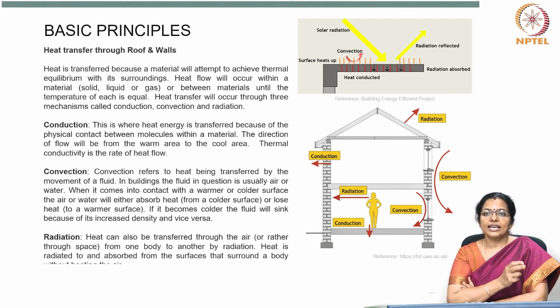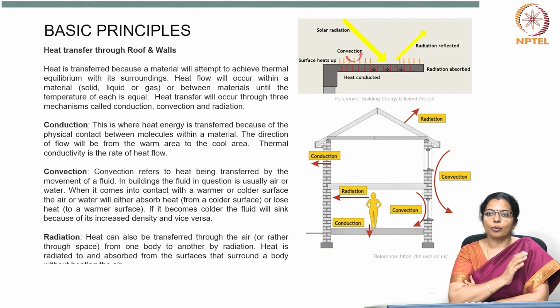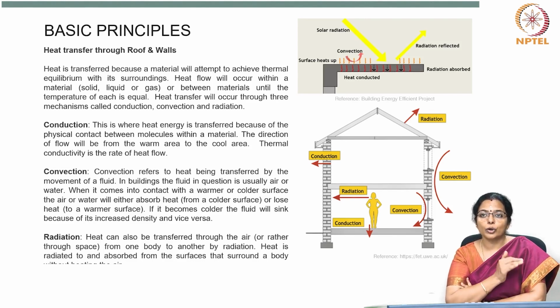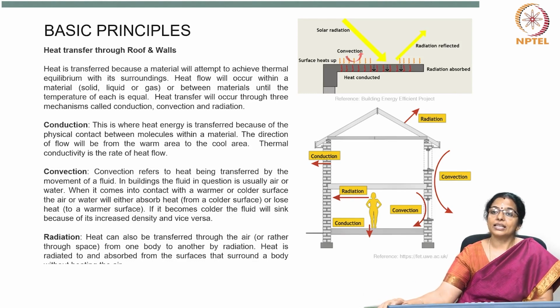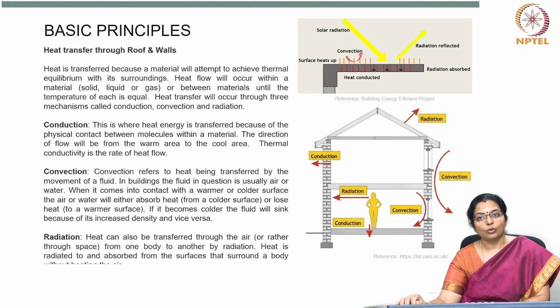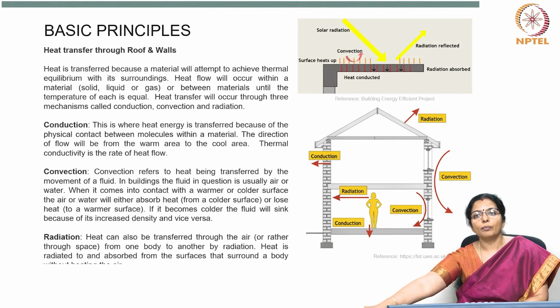That is, heat will be transferred from the body to the concrete more quickly than to the wooden floor because concrete is a better conductor. The concrete floor will be less thermally comfortable than the wooden one, although in fact a ground bearing concrete floor usually offers better thermal insulation.